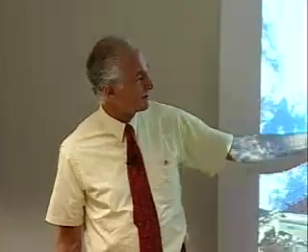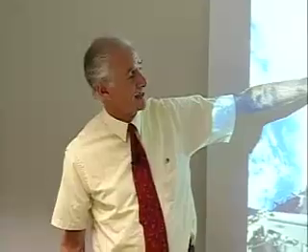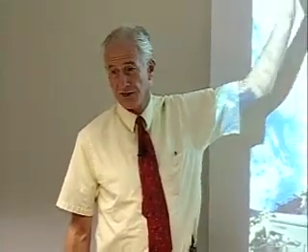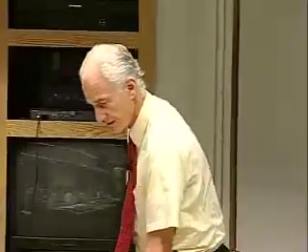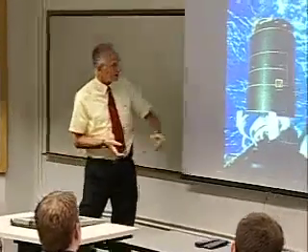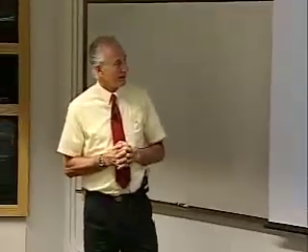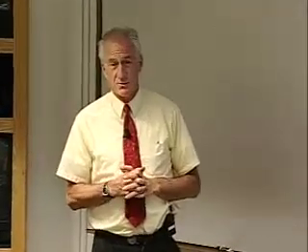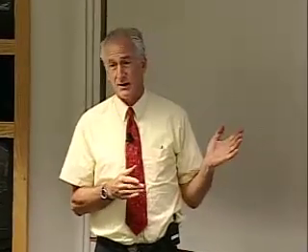And just a quick reminder of all the different things that we've used the orbiter for. Launching satellites, you've seen that picture. This is a payload assist module to take the satellite from the shuttle orbit up to geosynchronous transfer orbit. We have used it extensively for satellite repair in orbit. This is the Intelsat, where it was put into orbit by an expendable rocket, but into a bad orbit because of underperformance, and they managed to get it into a shuttle-compatible orbit.